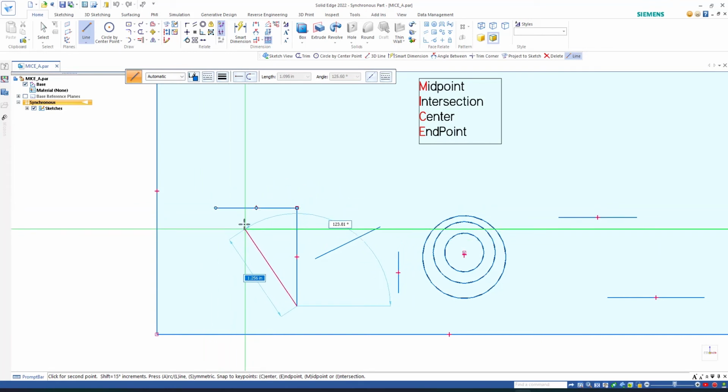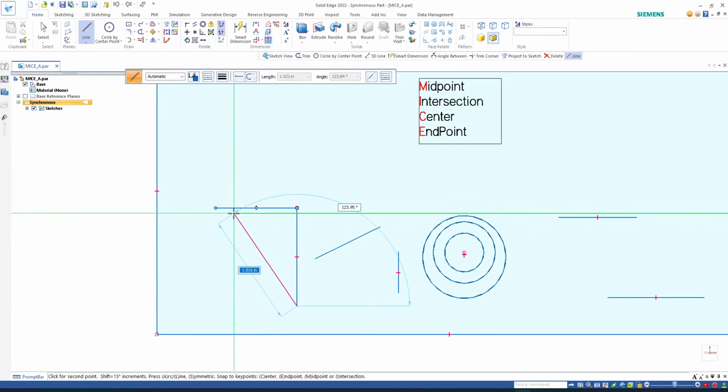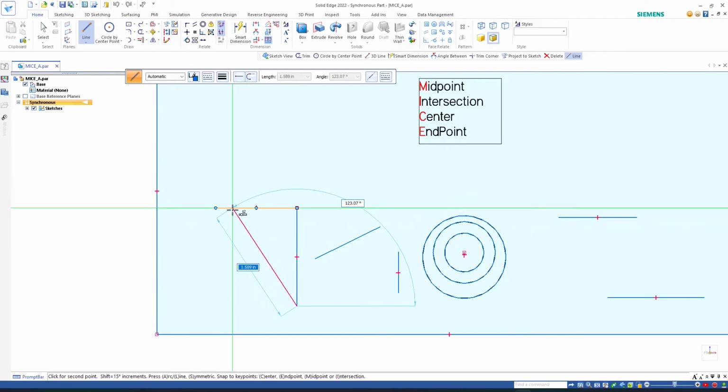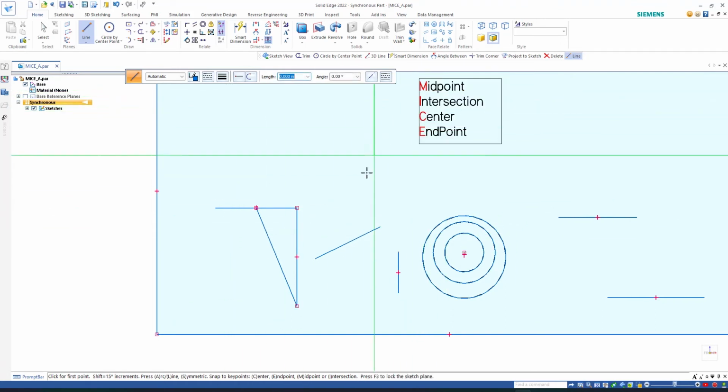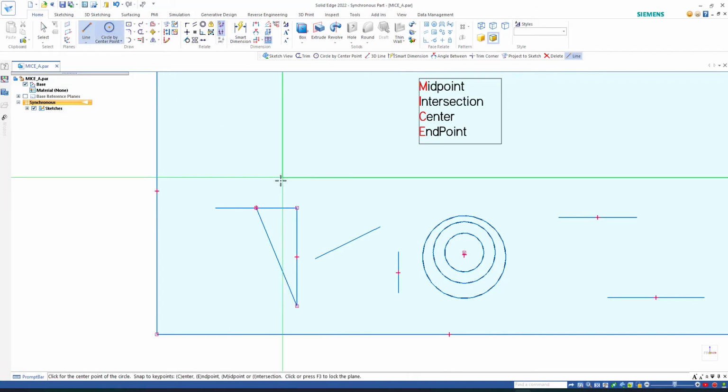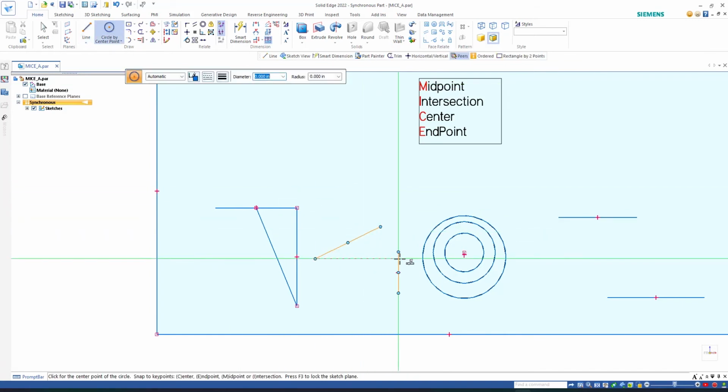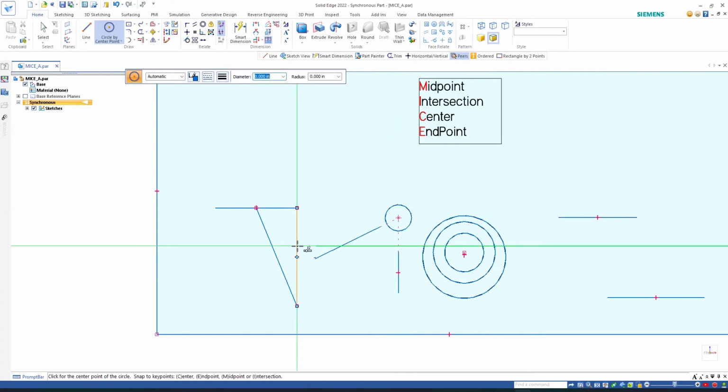But sometimes when you have a lot of lines and you want to just hover the one that you want, hit the M, and it just snaps right in there. That's the midpoint of the intersection. Let's say I want to draw a line here. For this one, you can just hover both of them and kind of hover over here and you get that indication. Left click there.